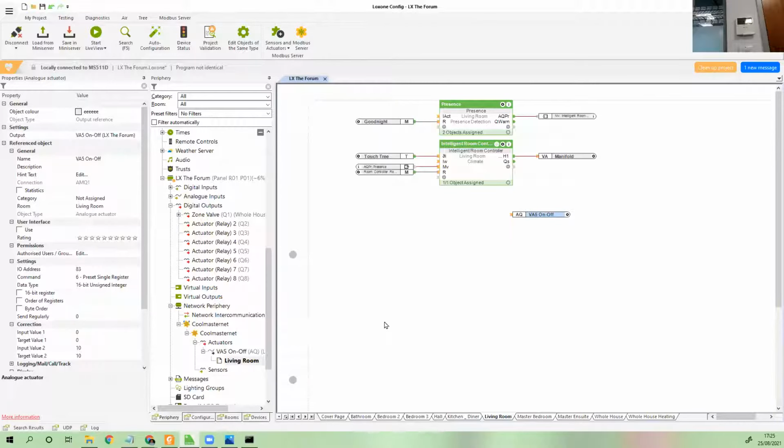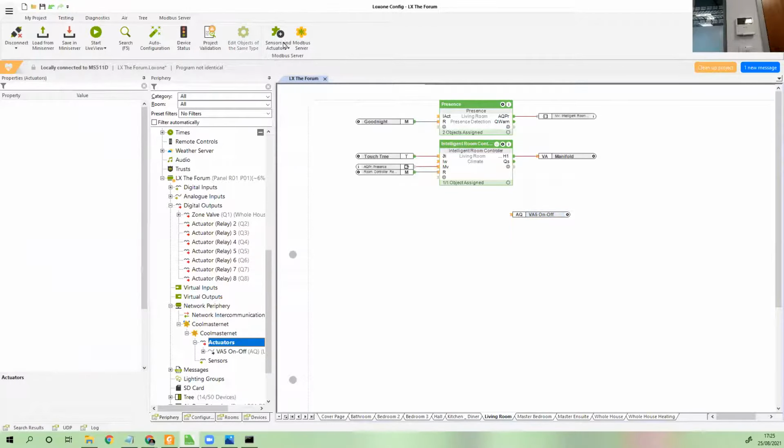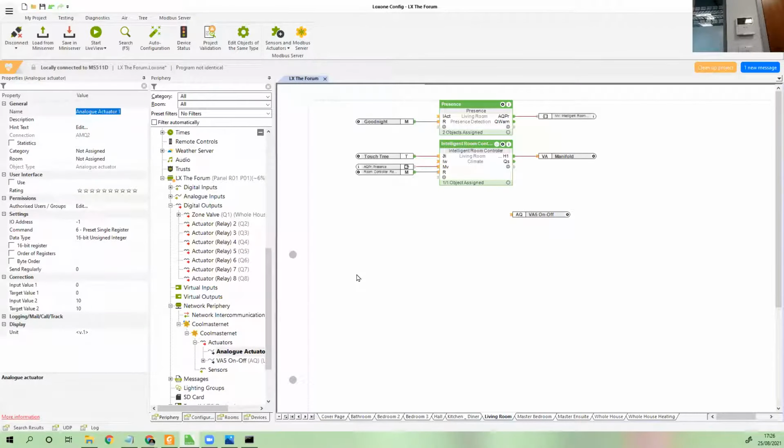As well as being able to turn it on and off, the other things that I can tell you straight away on every aircon unit you will need to be able to set is the operation mode. The operation mode is whether it is in cooling mode, heating mode, or automatic mode. Because as well as turning it on and off, you need to be able to say which operation it's going to. So that is an absolute must. On nearly all aircon units, you are also going to need to set the fan speed. Because pretty much every aircon unit has different fan speeds.